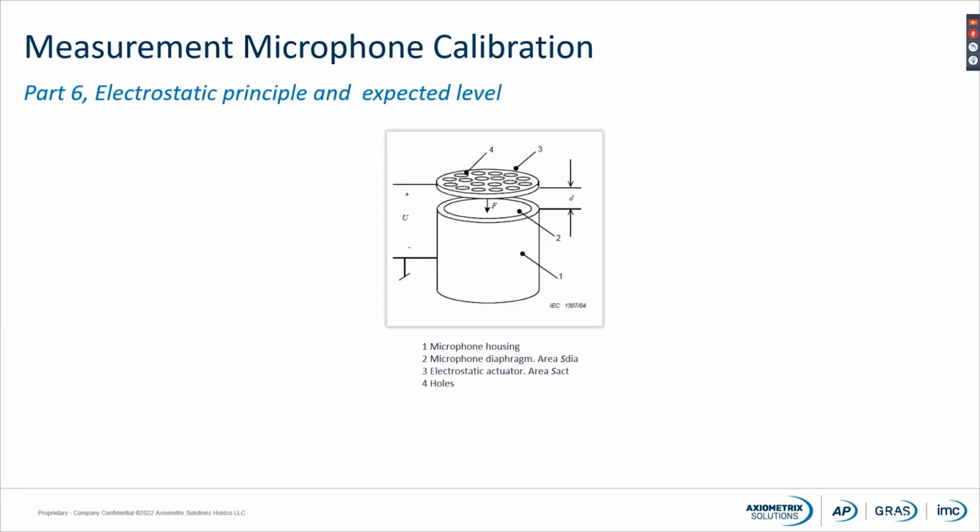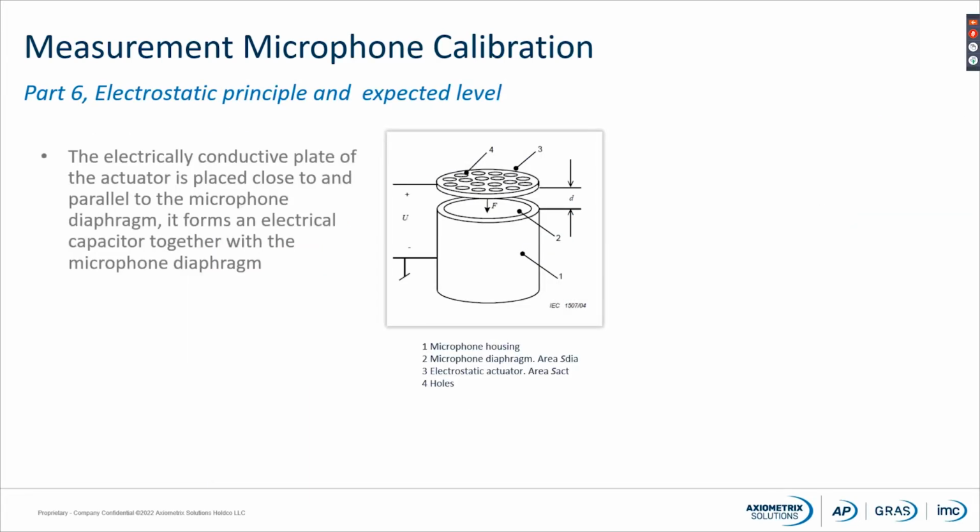If we look at the electrostatic principle, the plate of the actuator will be parallel with the microphone diaphragm, and it will therefore create a capacitor between the microphone diaphragm and the plate. So we are actually adding a capacitor on top of the microphone, so to say.